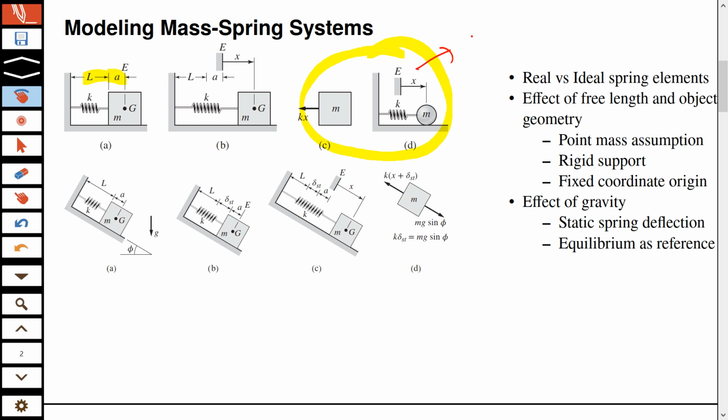So I'll just write the second law, which is always written for a rigid body. So it's mx double dot, and the only unbalanced force here is kx. Although in the diagram the arrow was helping me because these arrows are opposite, so I don't need to care about the minus sign, when I'm writing an equation, the equation needs a reference, and here the reference is, let's say, x double dot. So this kx I know is opposing that, so it will be minus. Okay. So if this is plus, this has to be minus.